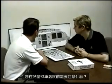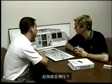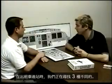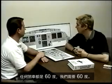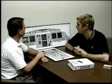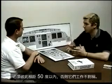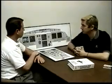Brakes. What are some brake temperatures that you're looking for before takeoff or even taxi in? Before takeoff, the maximum for takeoff is 300 degrees. On taxi in, we're looking for 3 different ones: 60, 150, and 600. 60 degrees is on any brake, we need to have 60 degrees. If it isn't, then the puck never engaged. 150 degrees is the difference between the pucks on each truck. Be within 150 degrees of each other, or they're working asymmetrically. And then 600 is the maximum on taxi in.